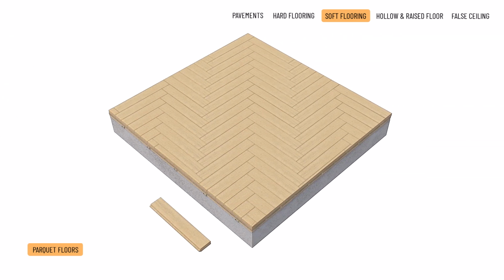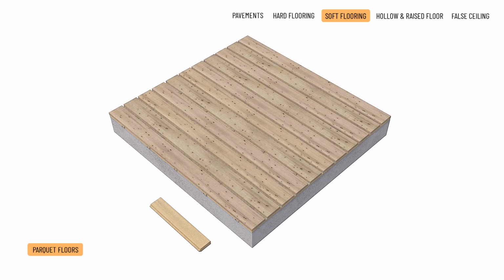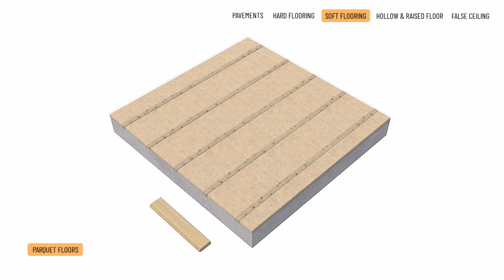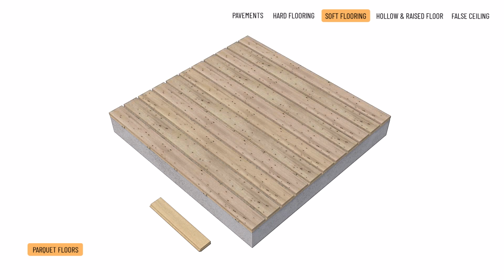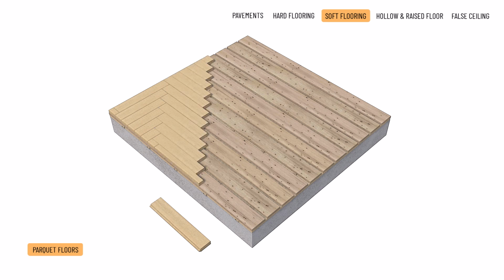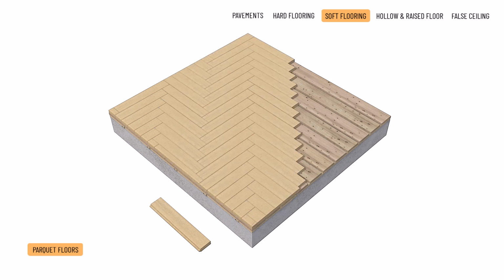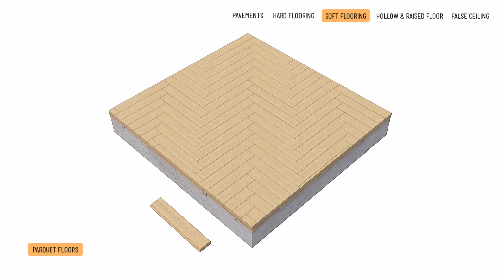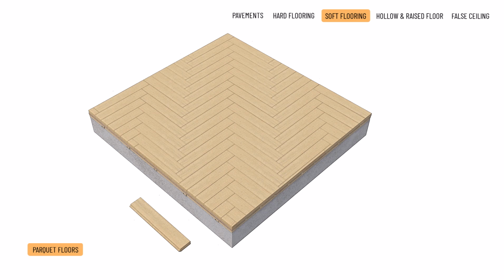Among the traditional solutions, the most common is the tongue and groove system, in which the parquet elements are nailed to a loosely laid subfloor resting on wooden battens, creating tongue and groove joints between the parquet elements. The finished surface has to be sanded and is typically coated with lacquer.